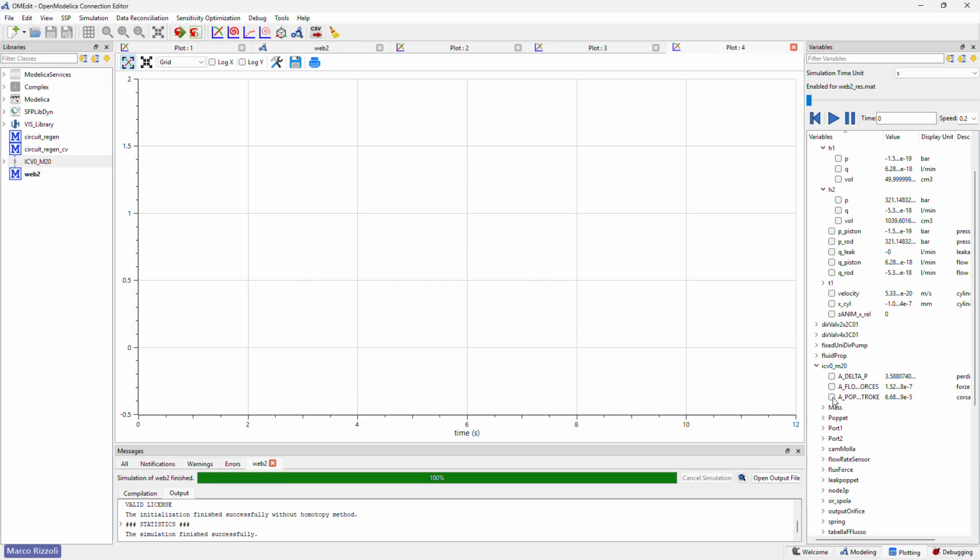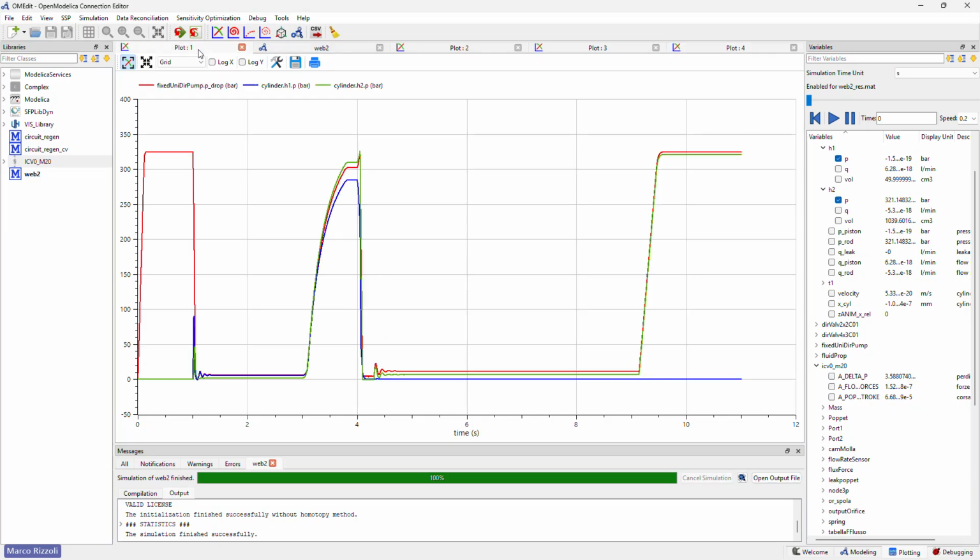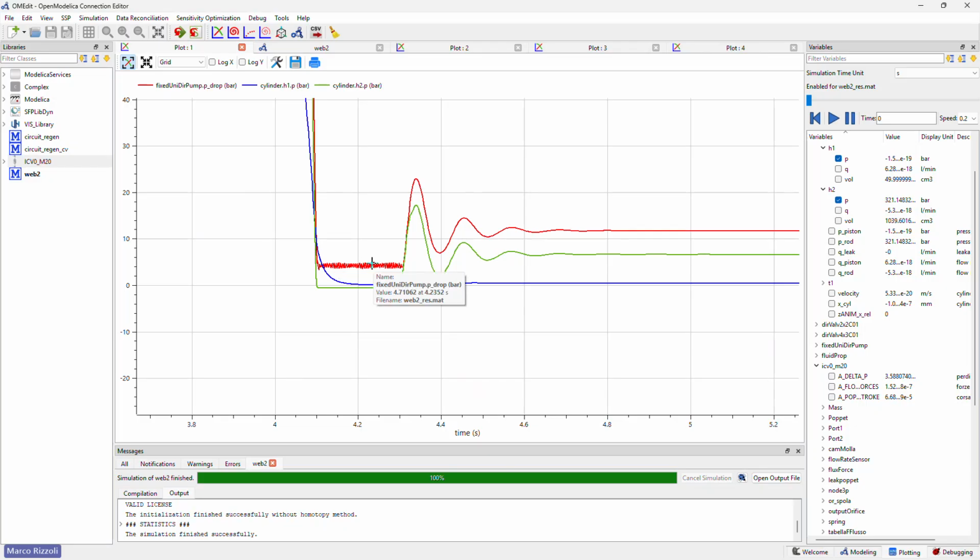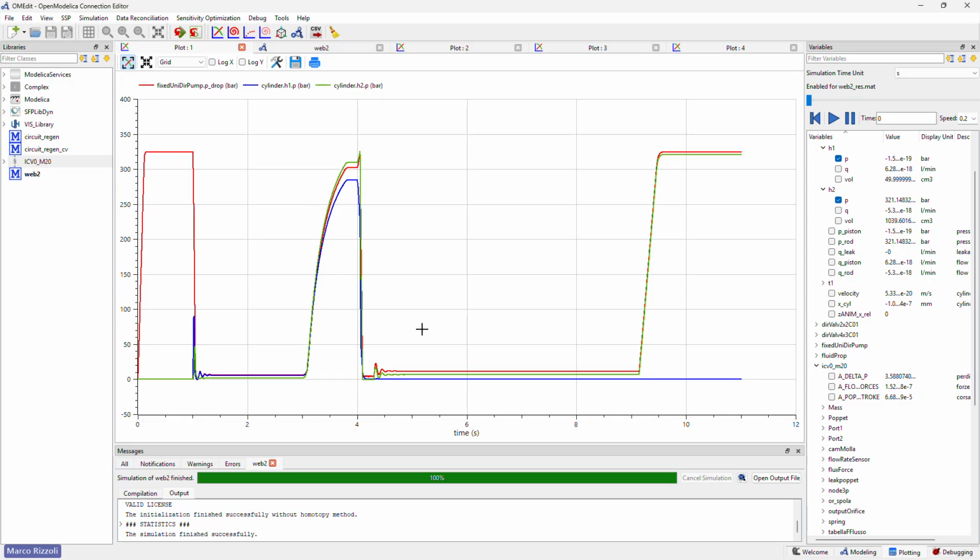The position of the poppet here is the movement that the poppet makes inside. Also, for example, the chattering, yes, probably it is because of the rapid switch that we have in the command, since we were still exiting and then we command the retraction, so we have the balancing of the pressures, and we know that it is quite normal to have some vibration during this rapid movement in the system.